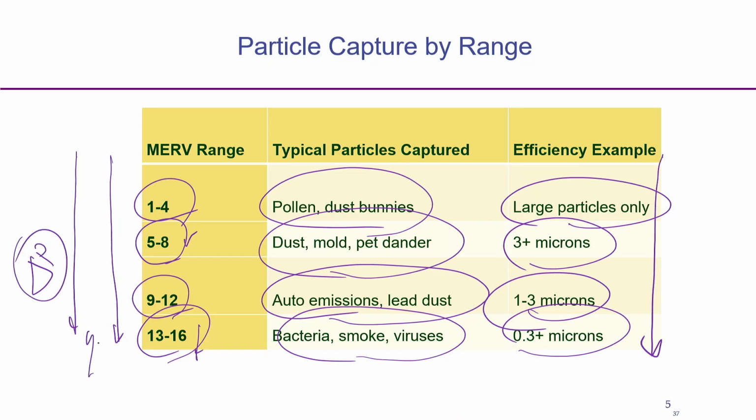Where we use high speed airflow, when the airflow rate is high, we should use the lower MERV range. But in a clean room or in a hospital the airflow rate is smaller, so in that case we can go for the higher MERV rating.